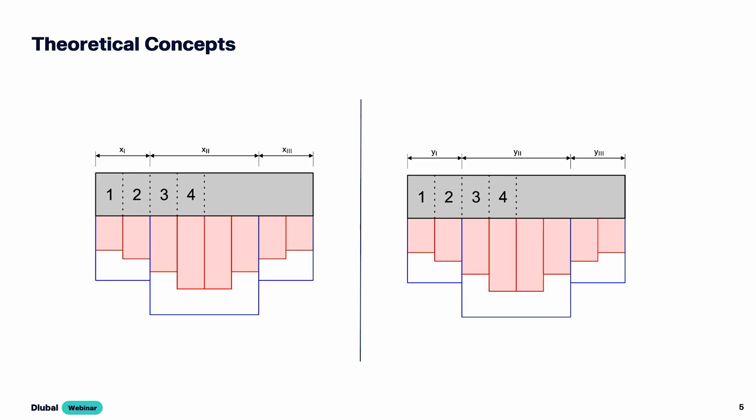And for each strip, the required reinforcement is calculated individually. And for practical reinforcement definition, the strips are grouped into 3 reinforcement areas, defined with x1, x2, and x3, and the same in the y direction.